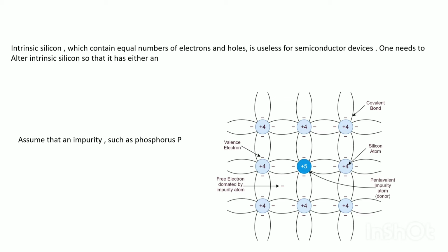Energies. What is interesting is that the hole behaves like a positively charged particle whose charge is equal and opposite to the electron. It is influenced by an electric field like an electron but travels in the opposite direction, more slowly than an electron, because of the effects of energy such as heat and light. Equal numbers of electrons and holes are produced in a semiconductor. This action is referred to as intrinsic generation of electron-hole pairs.